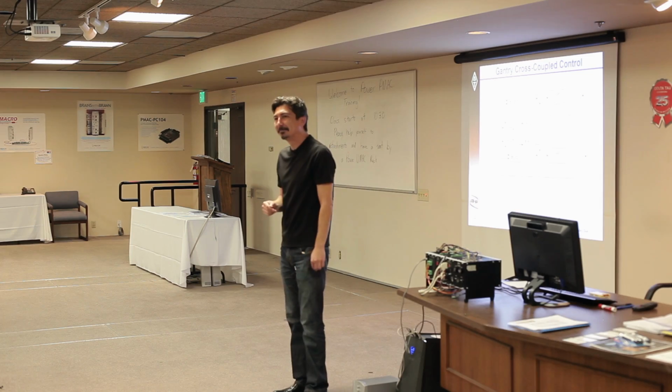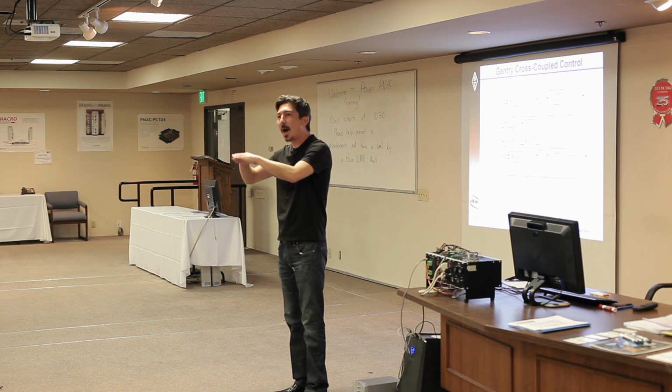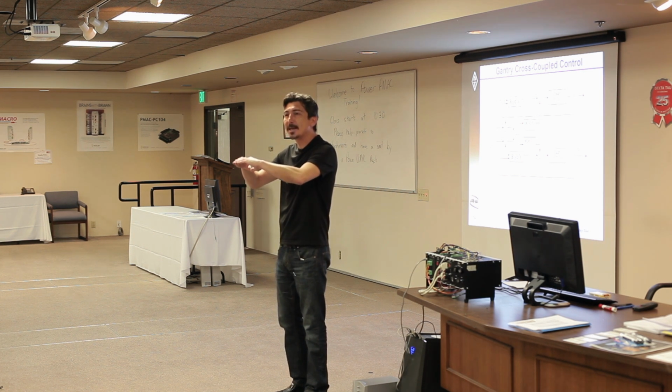Actually, we did it. We used trajectory prefilter. We found out the frequencies from the accelerometer they have on Z, looked at the X and Y accelerations also, and did a prefilter. Actually, we used like 2 notches. And the vibration was down to less than 50 milli-Gs.